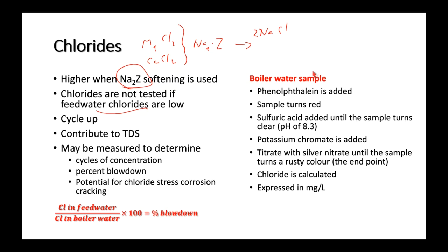They're balanced, both the calcium and the magnesium. Okay, so here, this is our feed water now, our makeup water. We've got chloride, we've got chloride. We don't really care too much. It's not scale forming because it's a sodium compound.